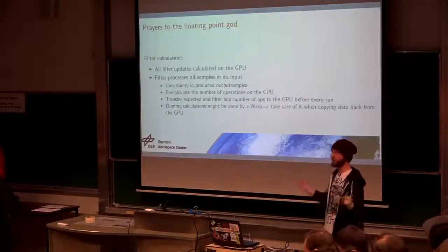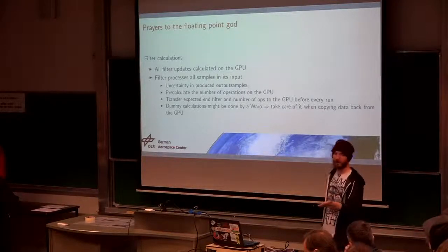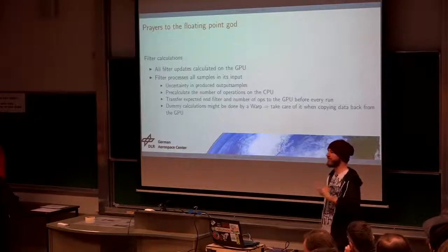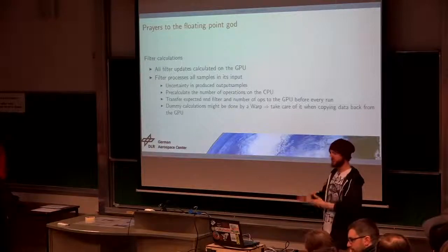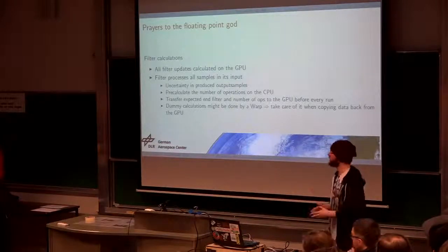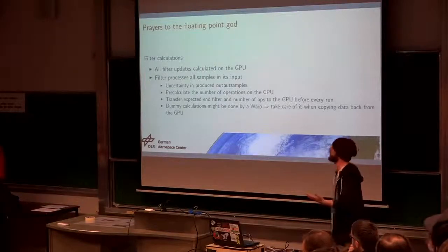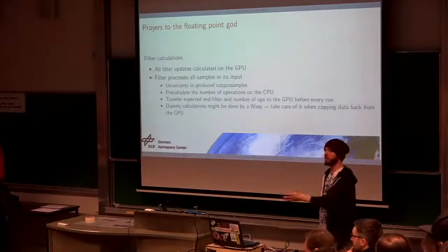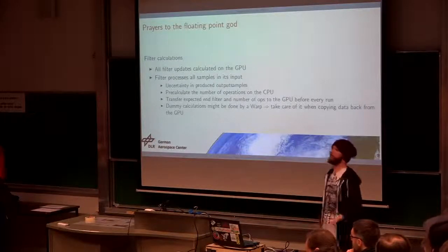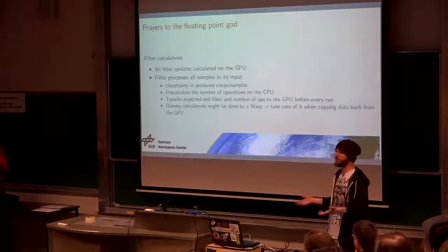I wanted to process all input samples at once, which means with an arbitrary resampler we have a variable number of output samples, which also means I don't know how many threads to start beforehand. So I pre-calculate on the CPU how many samples I will produce in this round, transfer that to the GPU, and then basically pray for two things.